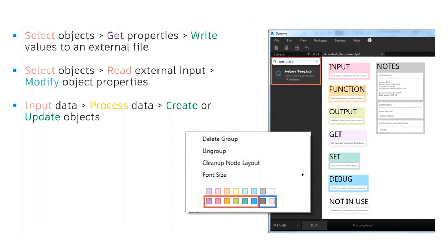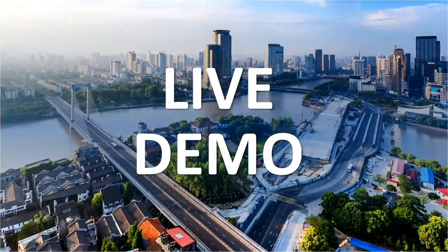You can definitely have different groupings so that later on, when someone created the script and you come as a designer, you are using it yourself. You see, for example, this is for debugging. This is for creating an output. This is for the input, reading from a CSV file or reading from a DWG file. So it has many tools to automate the process.